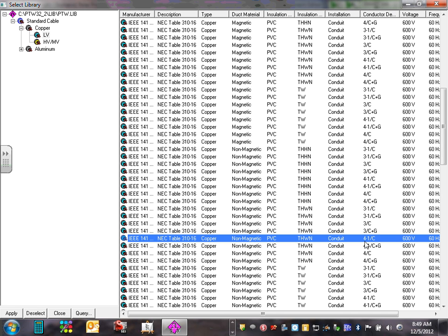Look at the one above it. Actually, the one right underneath it with ground. Do I need a ground? No. Between the service and the box, no ground is needed. That's where the neutral doesn't play a whole lot of role. So we just assume it's going to be the same size here. Good point. Full size. Give me 1 second. Everybody's okay with this? How I choose that one?